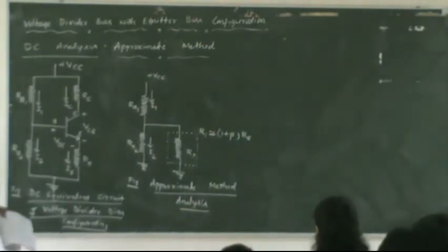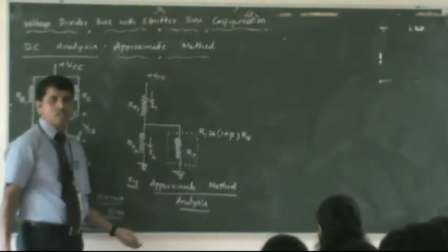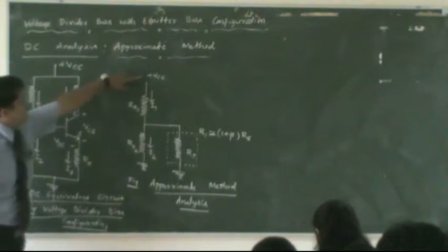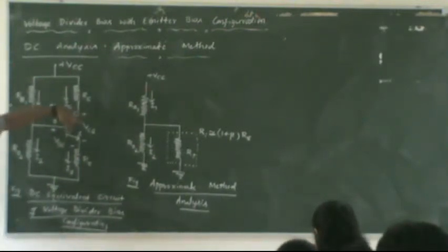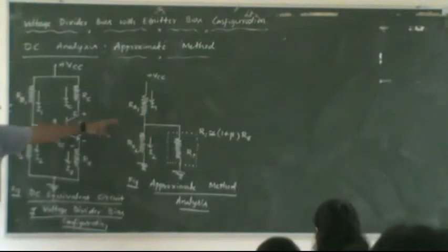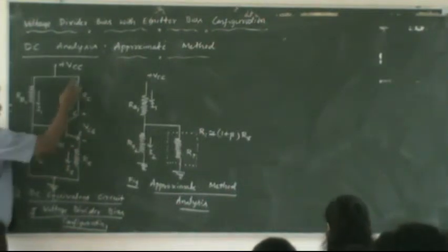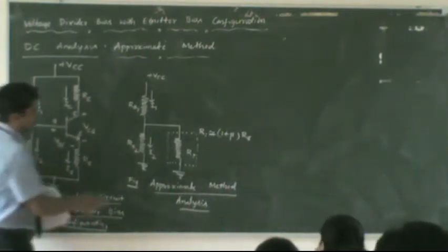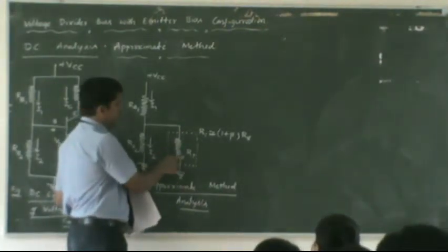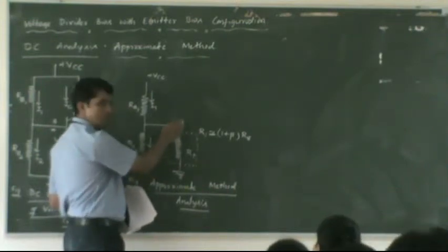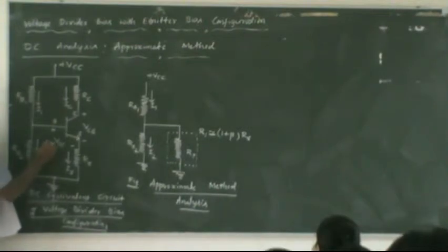Okay, look at the approximate conditions here which you need to satisfy. Any questions while drawing this circuit? This is not a complete circuit, and look at what we have done here. This VCC is retained as it is, no changes, and RB1, RB2 as usual you can see there. The currents are also written the same, whatever is flowing. But for the rest of the circuit, the transistor at this particular point, when you look into the input side, what is the resistance offered by the circuit?